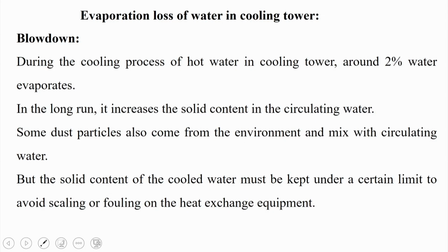So, in the long run it increases the solid content in the circulating water. Some dust particles also come from the environment and mix with the circulating water, but the solid content of the cooled water must be kept under a certain limit to avoid scaling or fouling on the heat exchanger or equipment, or anywhere this cold water will be used.